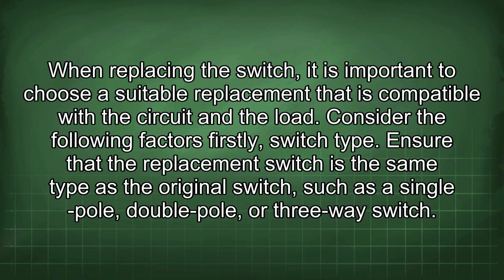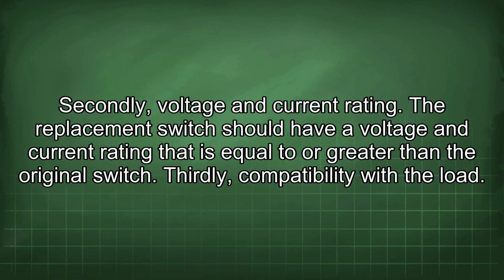When replacing the switch, it is important to choose a suitable replacement that is compatible with the circuit and the load. Consider the following factors. Firstly, switch type. Ensure that the replacement switch is the same type as the original switch, such as a single pole, double pole, or three-way switch. Secondly, voltage and current rating. The replacement switch should have a voltage and current rating that is equal to or greater than the original switch.